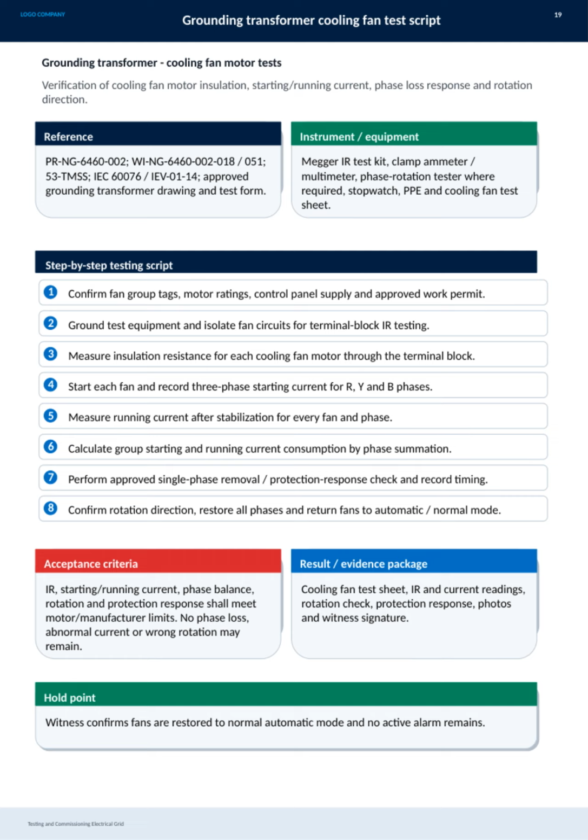The hold point is when the witness confirms fans are back to normal automatic operation with no alarms active. This thorough process ensures the grounding transformer cooling fans operate reliably and safely.